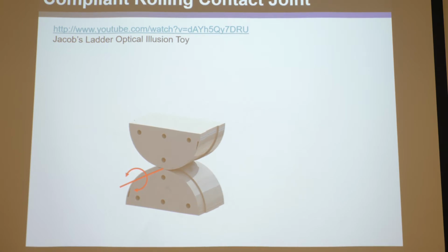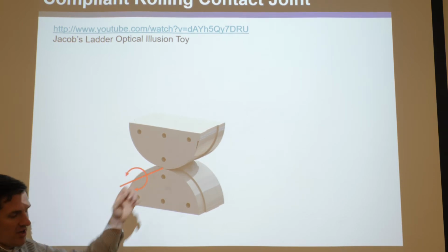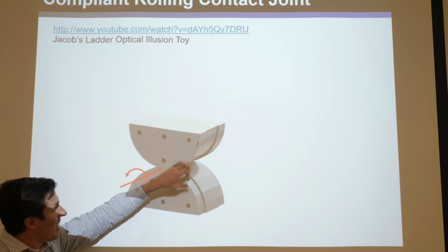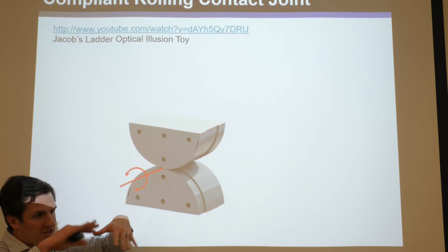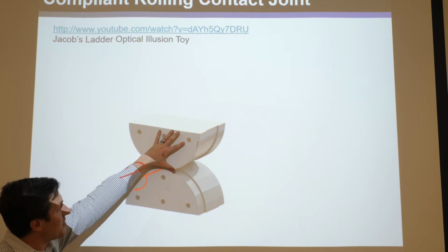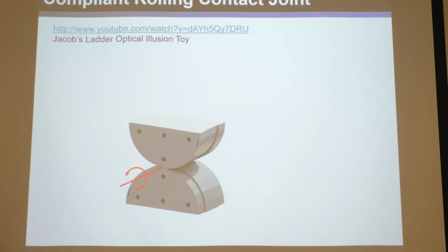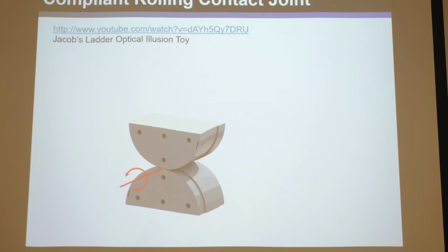And it's really remarkable because most compliant joints are limited in range. As you deform them, they increase in strain, start getting to yield strength, and they break. Well, as you deform these in place, they reach some stress that's below their yield strength, but then no matter how much you rotate it, independent of its position, it never increases in internal stress.